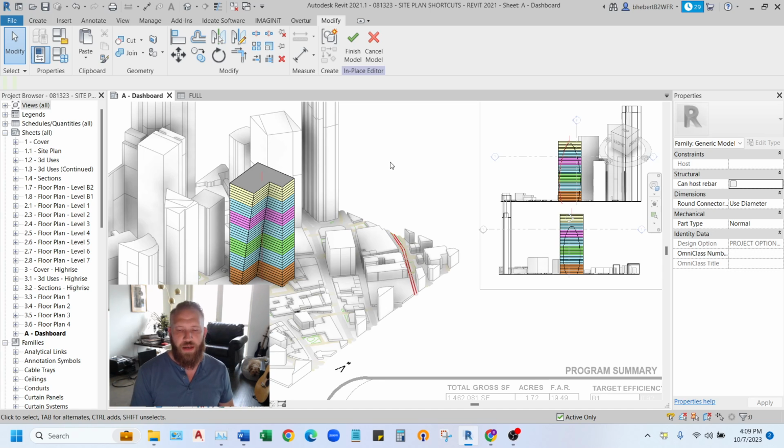Today I'll be showing you how to sculpt your buildings by using ceilings and void forms in Revit. The reason that we're using ceilings in this template is because when you give ceilings thickness, you can give it like a 12-foot thick ceiling thickness that can represent a floor of a building as a massing. And the reason that's better than using a floor is that when you start your ceiling, it actually propagates upward as you give it thickness. So when you put your ceiling on the first floor, it's actually going to represent your first floor massing, rather than if it was a floor, it would represent a basement floor kind of under the ground or whatever.